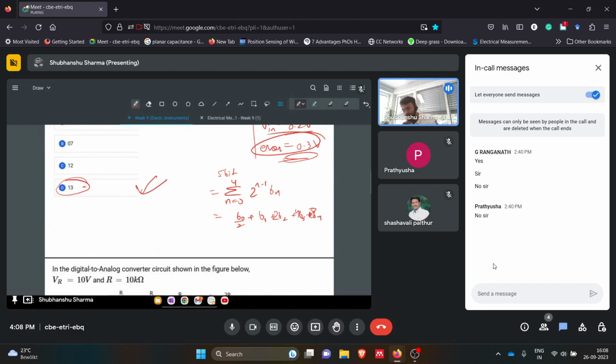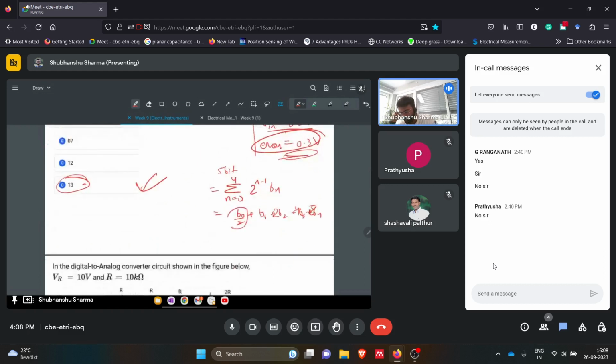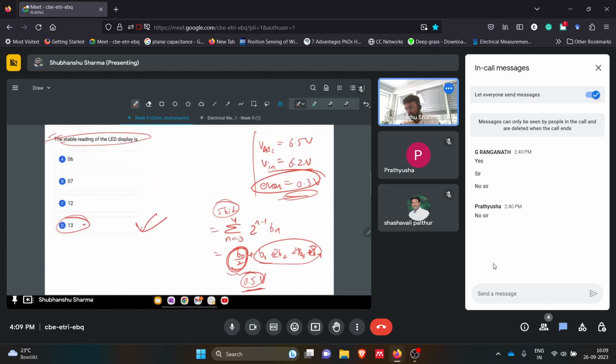I don't think so, because the step increase is being decided by the lower bit of this DAC. If b0 is 1, it is again 0.5 volts. So again, anyway this will be increasing in 0.5 volts. We cannot get more resolution by just simply increasing the bits. That is one observation. Okay, we failed in that, but then how else can we improve this?